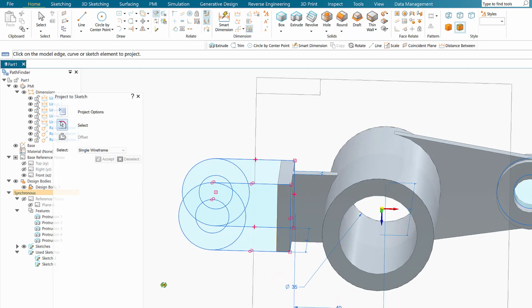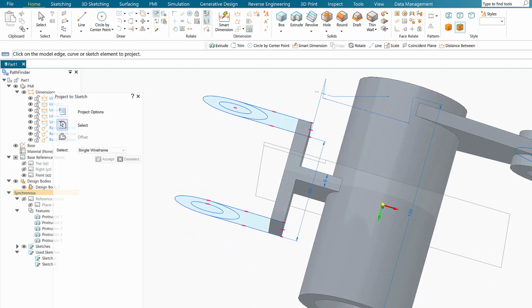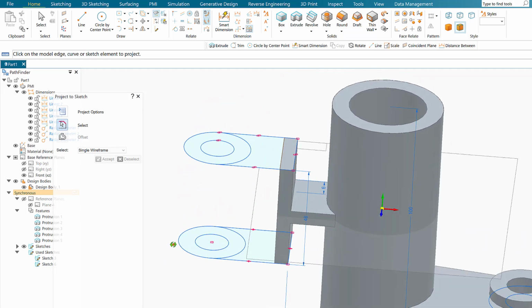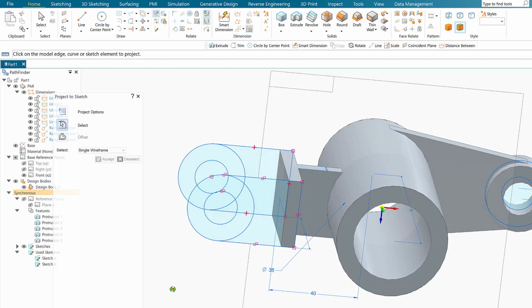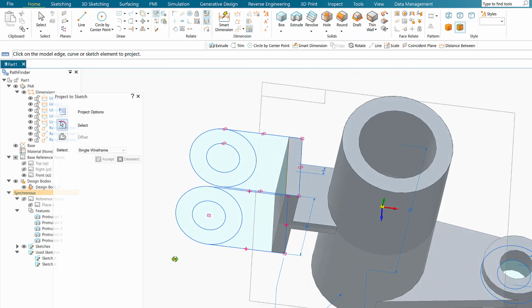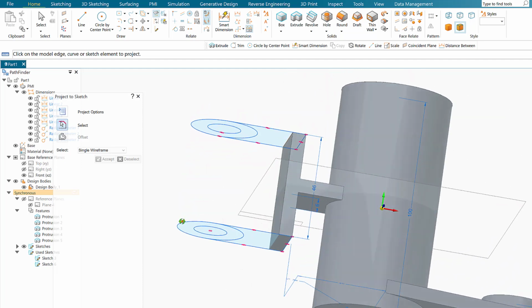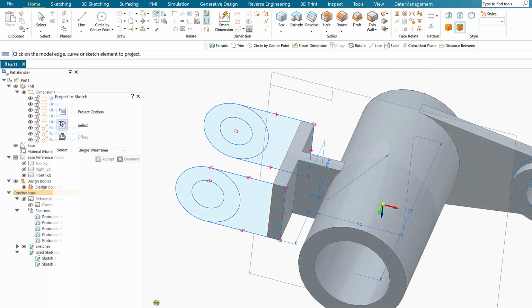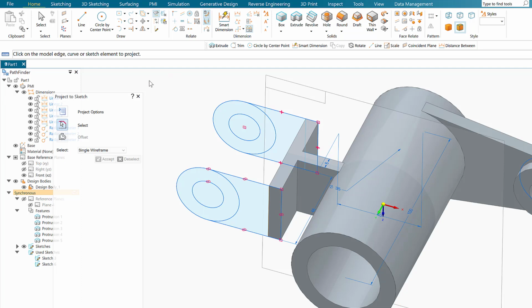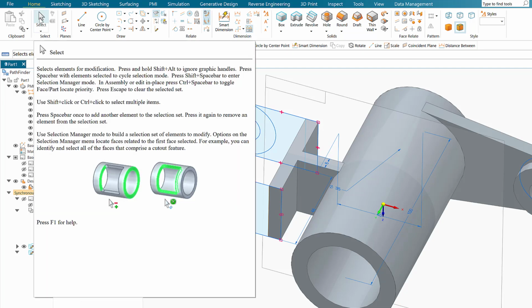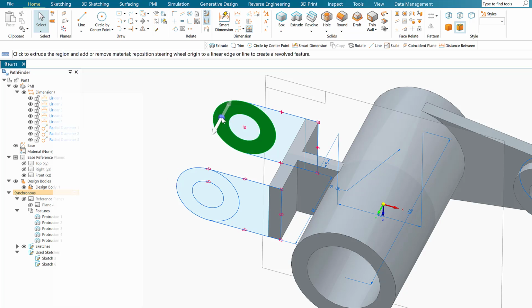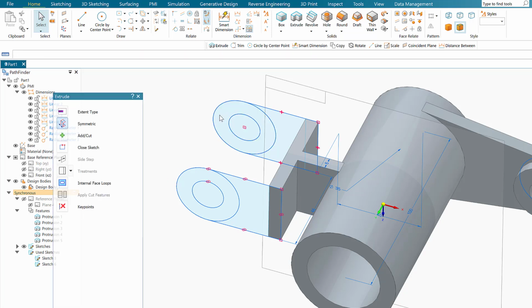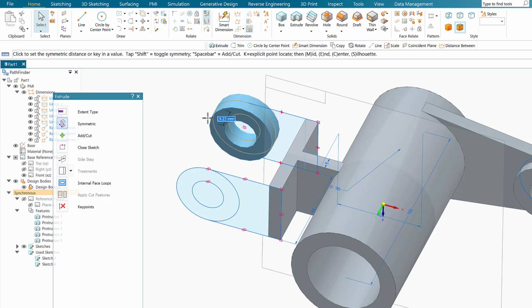So this way I was able to draw the same sketch to the other side. Or what you can do, the quickest way, you can highlight the whole sketch and just click it once, and that's it. You are done in one step. Okay, so now I'm gonna start what? Do the extrusion. This time, okay, I can do that. Okay, I can still use select, click on this one here, click, because this will give me a symmetric extrusion, and this should be 12. Enter.